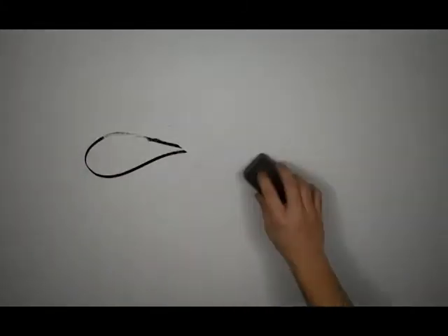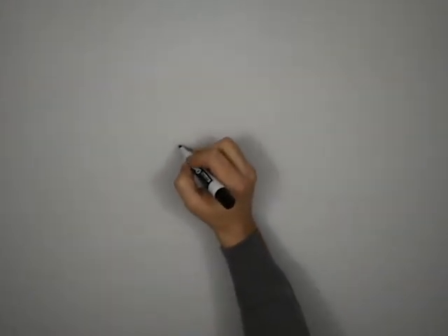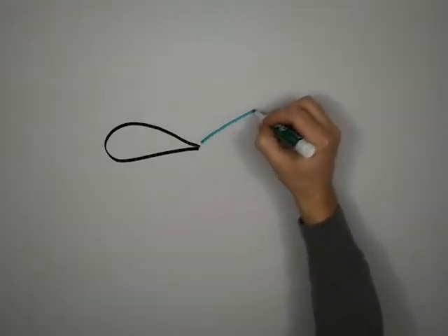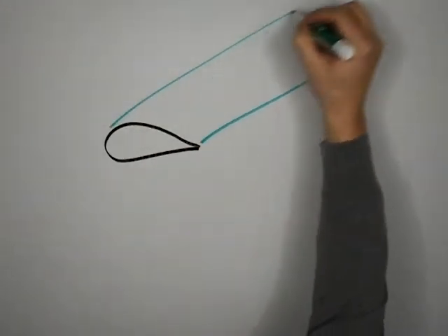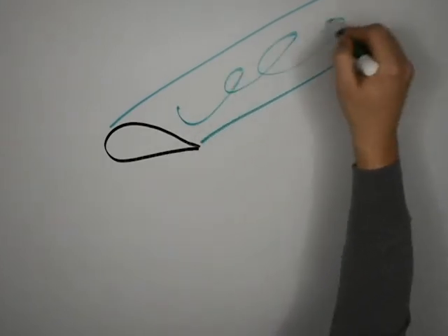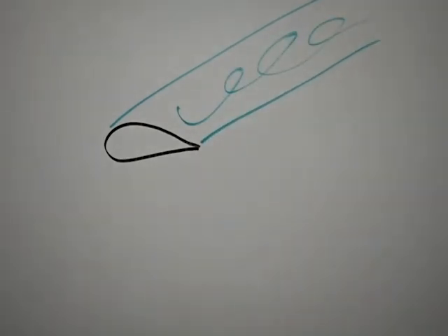The next thing on the to-do list is to explain where I got that 11.5 inches for the tail length in the beginning of the video. You can place the tail anywhere you want, but it's going to be easiest if you put it behind the main wing, like just about every airplane you've ever seen. There are 2 main things that we need to avoid when picking a spot to put our tail. This first spot in green shows an area that, if we were to get into a stall, would be very turbulent. Having turbulent air pass over your tail is going to cause it to not have any control, and it'll be very difficult to recover from a stall.